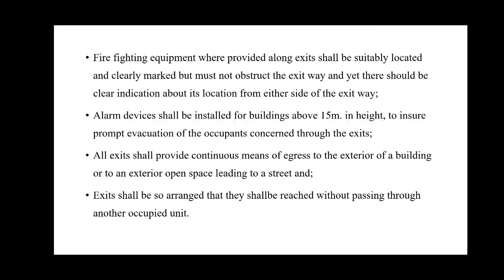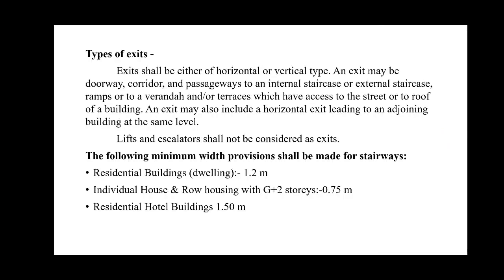All exits shall provide continuous means of egress to the exterior of the building or to an exterior open space leading to a street, and shall be arranged in such a way that they shall be reached without passing through other occupied unit. Types of exits, as discussed earlier, should include either the horizontal or vertical type,